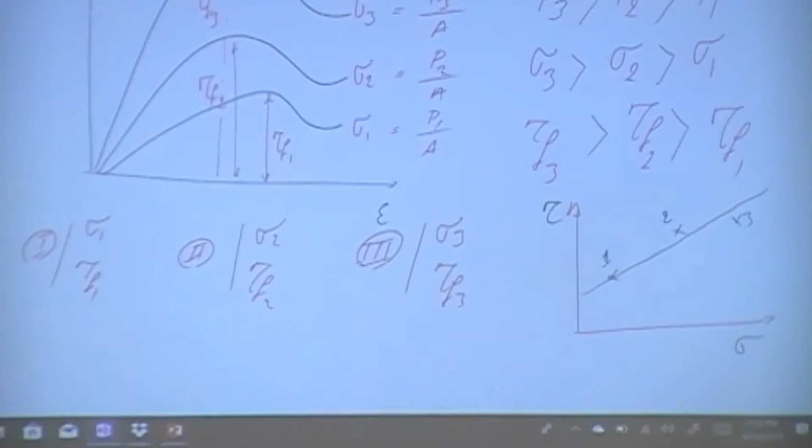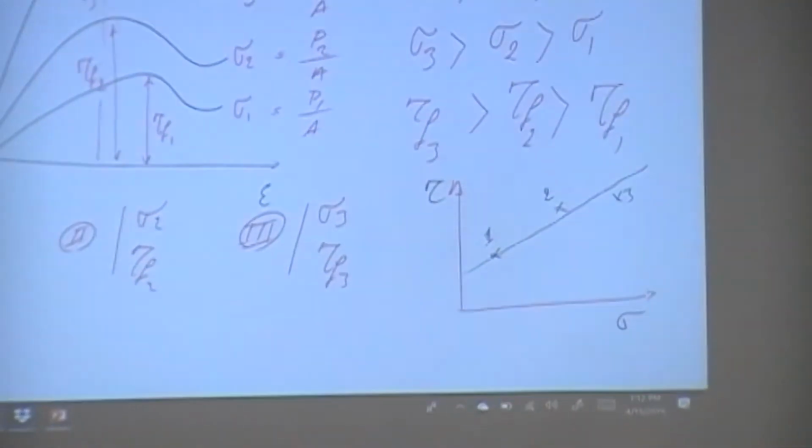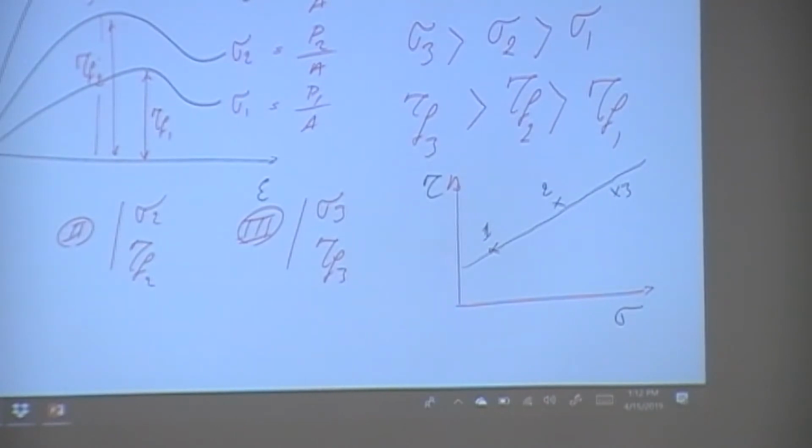Now you have the points that are basically lying along the failure surface or failure angle that you have. Now the rest of it is going to be very simple and straightforward. You have the C value here and you have the phi value here. And those are the parameters of your Mohr-Coulomb failure. That's how you determine that. Make sense? So that's basically the process.